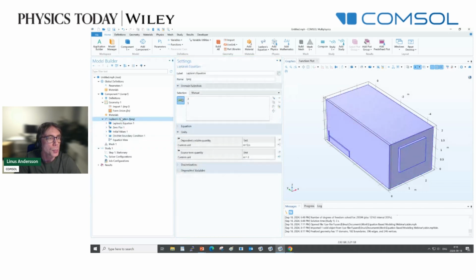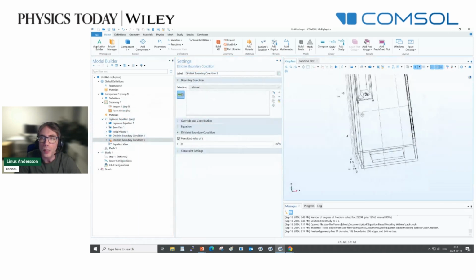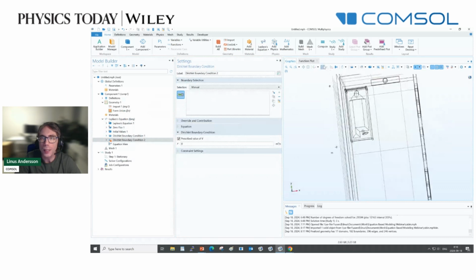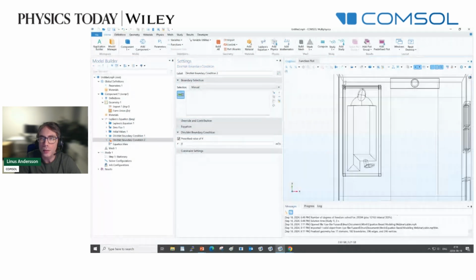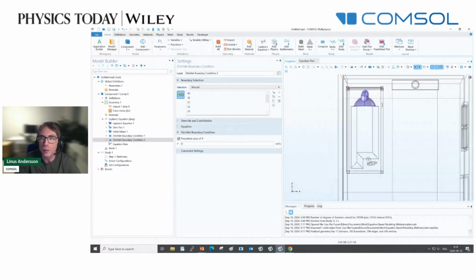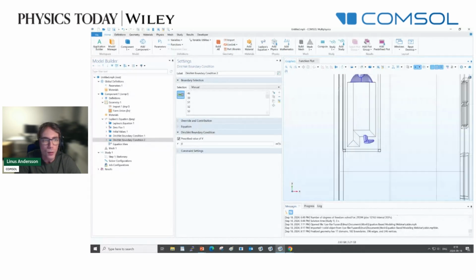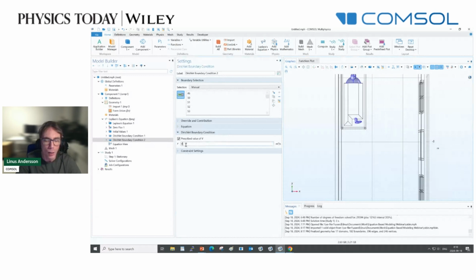So next, there's a boundary condition. I'm going to apply that to my skin. So I can use maybe an XY plane to easier select that, and select box tool like that. So this is one part of my body that sticks out of the blanket, and here's a very unfortunate little foot. It's going to hurt once we've solved this model. Right here, we're prescribing a different value of the attractor, 0.5.